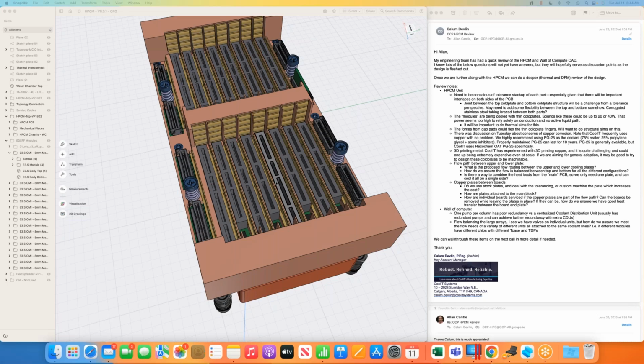But if you take a CXL.mem from Samsung, you have a controller sat down near the bottom, and then you have the memory chips in a similar fashion, or an SSD. You have a controller chip near the fingers again, and all the flash memory up and down the module. So it's that sort of layout you typically see, and the controllers typically burn a big chunk, like 50% or so, of the total power of the module, and the rest of the power goes to the media, which is distributed through the many chips.